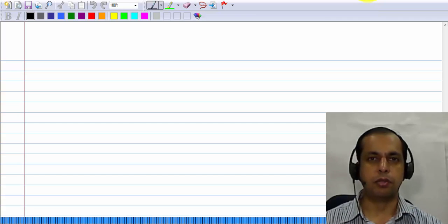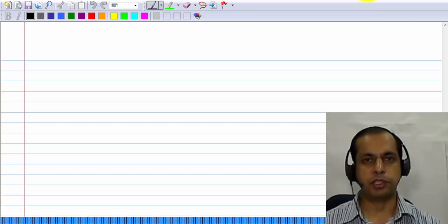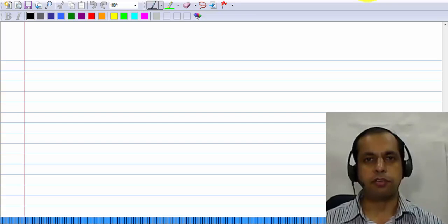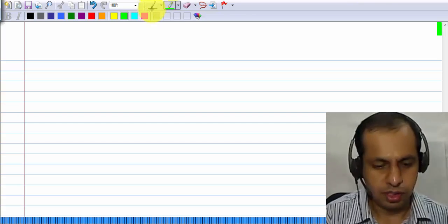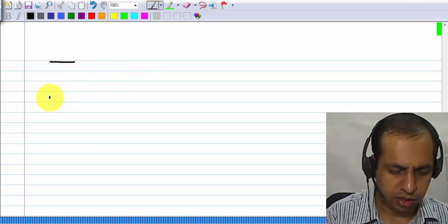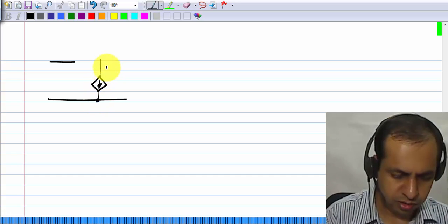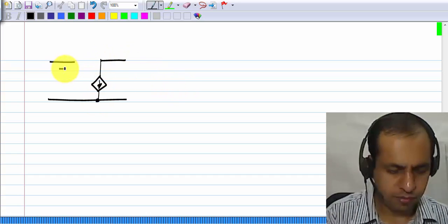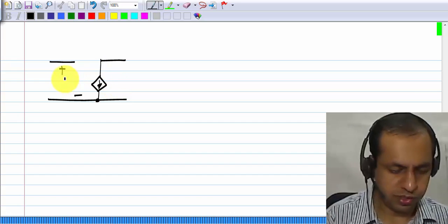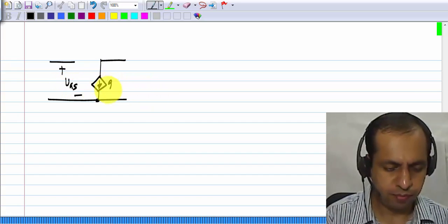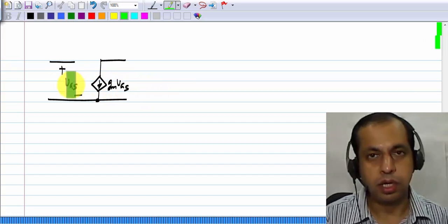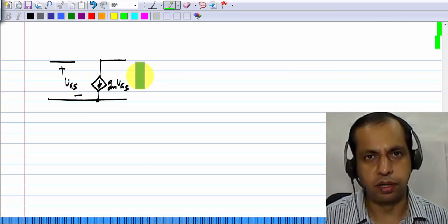We have discussed the common source amplifier and many different ways of biasing it. The common source amplifier is a native use of the MOS transistor. That is, the incremental picture of a MOS transistor is this, omitting the output conductance GDS. It is by itself a voltage controlled current source.